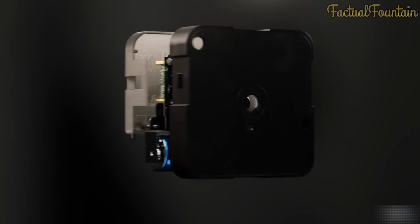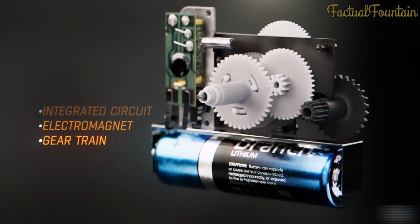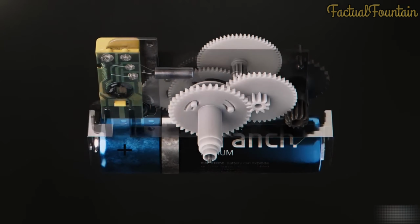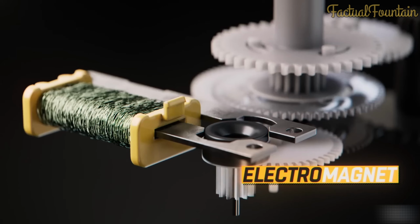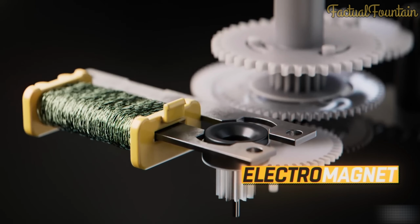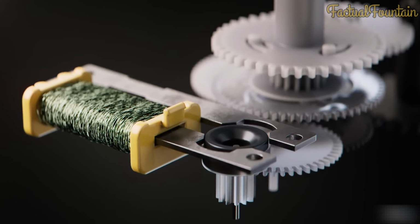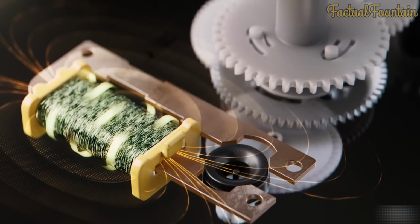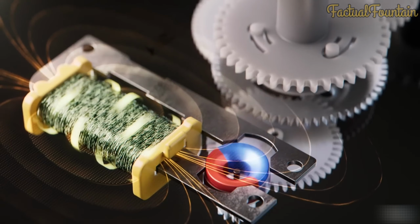Inside this $10 wall clock are 5 unique systems that enable it to work. The most recognizable is the Geartrain, made from 8 gears. At the beginning of the Geartrain, a driver gear is rotated by an electromagnet, which provides the force to rotate the clock hands. This electromagnet is composed of a coil of wire, which uses electrical current to generate a magnetic field, and a strip of iron to channel that magnetic field to the drive gear.